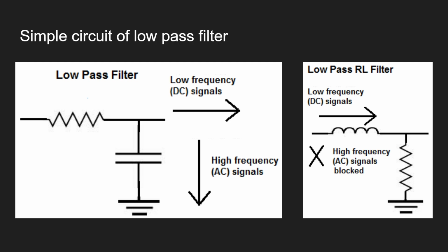So when XC is increased, frequency is low. That's why when we say that XC decreases when frequency is increased. So that's why we say that when the frequency is very high, the capacitor will have a very low impedance, so that the current and voltage will flow through it. Okay. So that the high frequency signal will follow the capacitor and be grounded. Do I need to draw it once again? You can see that now, or not?